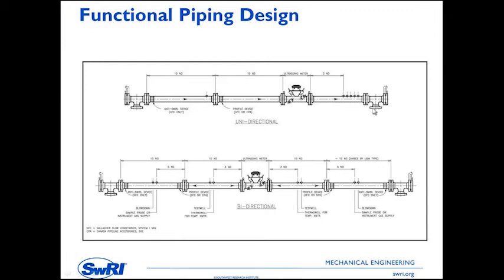So they tended to be stations in which you had multi-run orifice meters. Then when ultrasonic meters came along, we found that we could size these stations to have an array of tube sizes for the application and accommodate a significant amount of turndown.